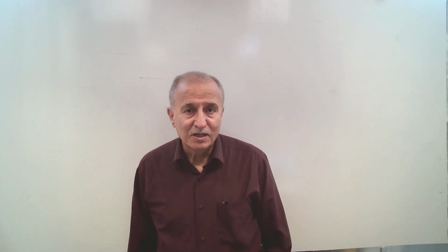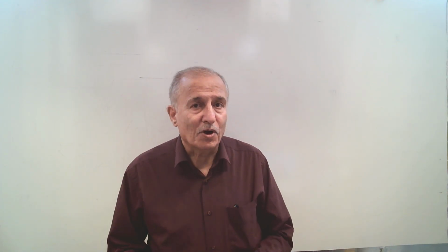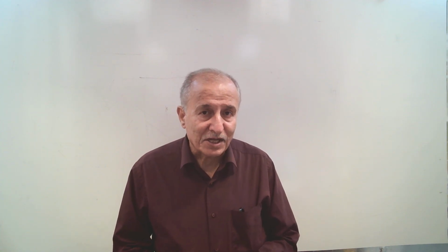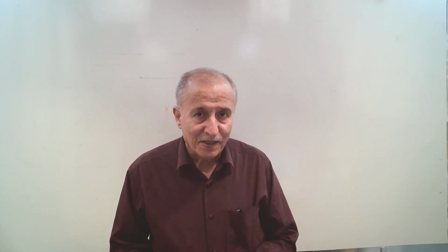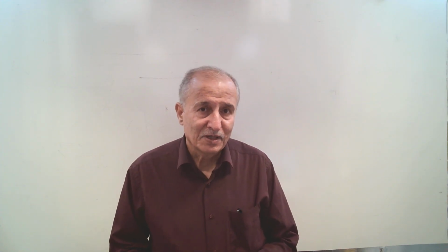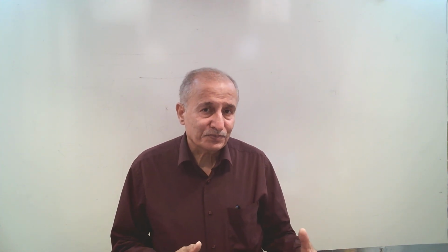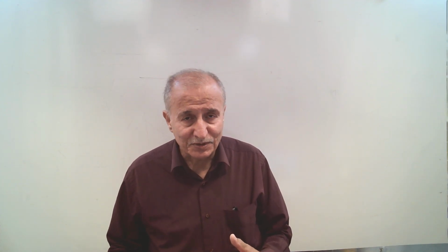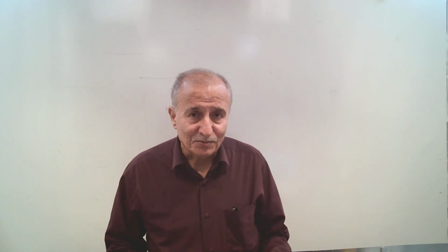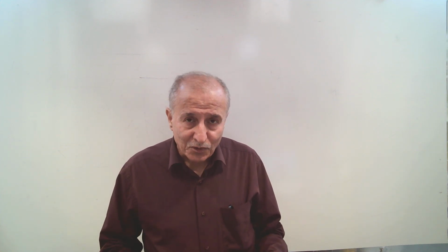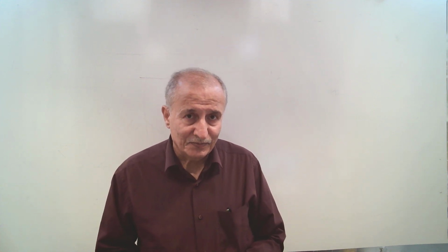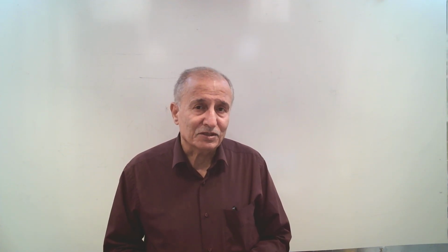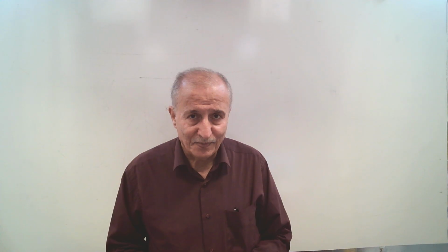I'm Mohsen. Today in this video we are going to talk about orientation controls in GD&T, geometric dimensioning and tolerancing. Orientation controls control the orientation of a feature and a feature of size with respect to a datum. It means parallelism, perpendicularity, and angularity. These are orientation controls. Let's today just talk about parallelism.